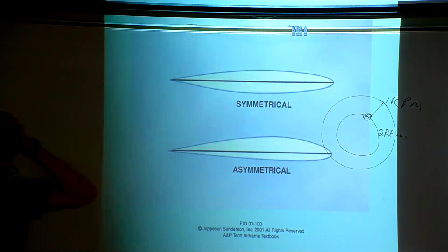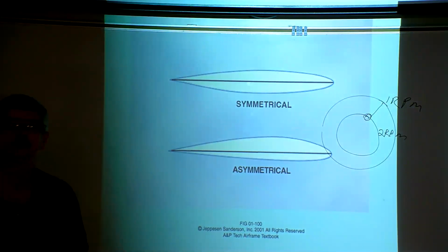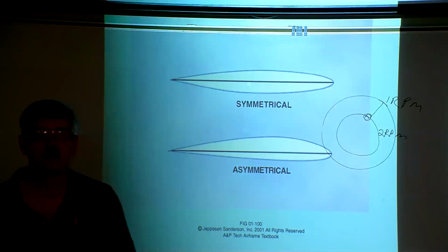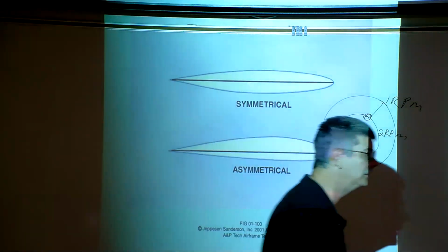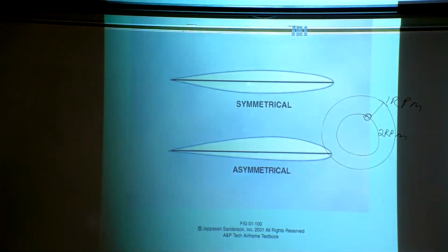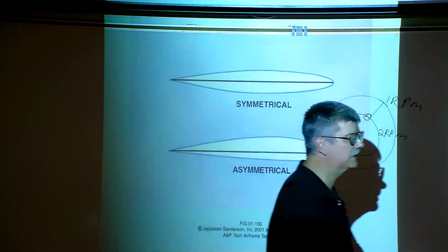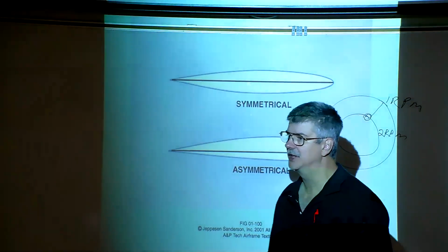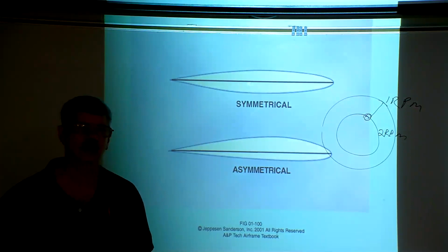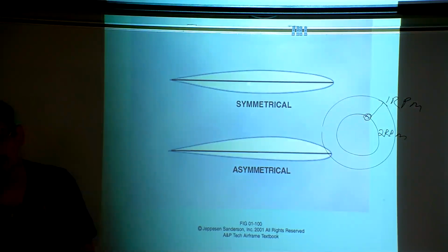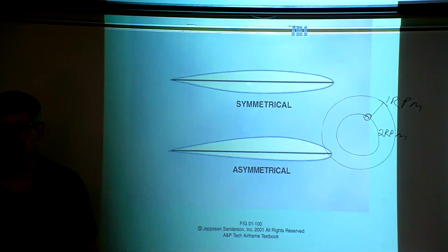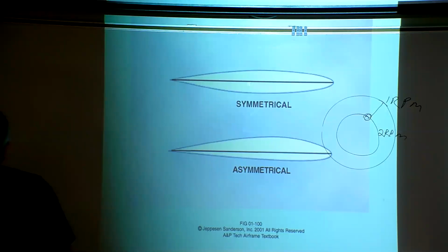All right. Are there any questions on the two gyroscopic forces? No questions. Okay. Just keep in mind, you might see a question: what type of gyroscopic force says that the force applied actually acts at 90 degrees in the direction of rotation? That's precession. The tendency for a spinning object to stay in the plane of rotation is rigidity in space. Okay.